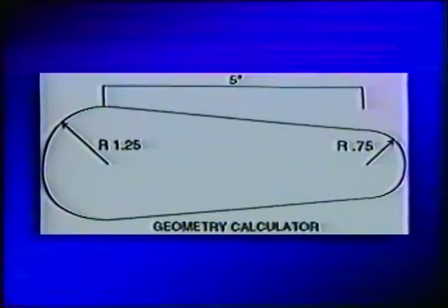So we go to the point definition, showing the intersection of two elements. When I select it, it asks me for the element numbers. The circle is element 1, and the line is element 3. I select those elements, and the point is input automatically. I repeat the process for the remaining tangency points until all of the intersections are found.